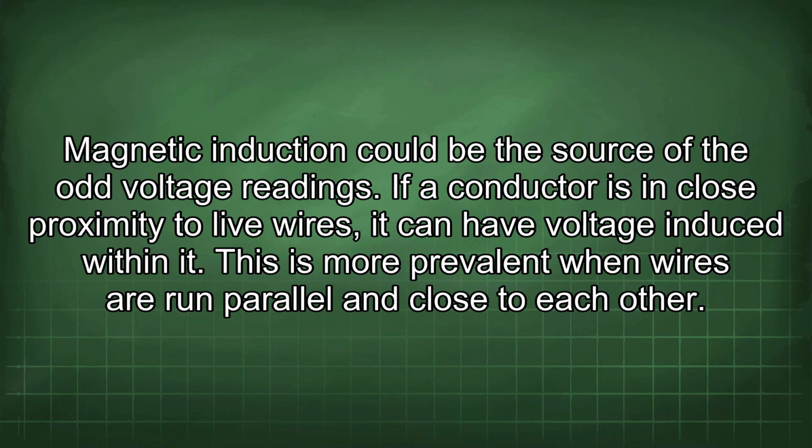Magnetic induction could be the source of the odd voltage readings. If a conductor is in close proximity to live wires, it can have voltage induced within it. This is more prevalent when wires are run parallel and close to each other.